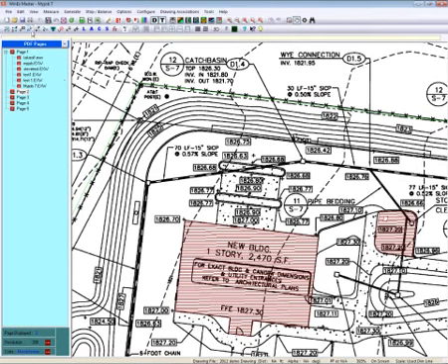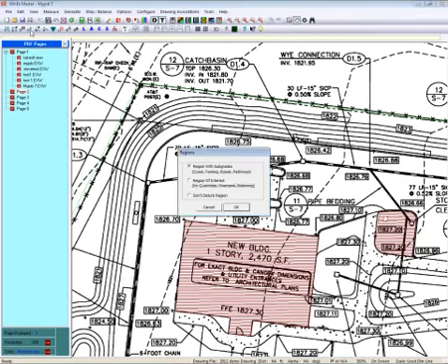If you need to, we have a very powerful, what we call regions selection. We can put in regions with subgrades. And remember, we think of regions as having changing elevations. So I can put in curbs, parking lots, roadways, and pathways. I could put in a region of interest. Say I want to put a landscaping area in. I'm going to show you in just a minute this entire drawing finished.